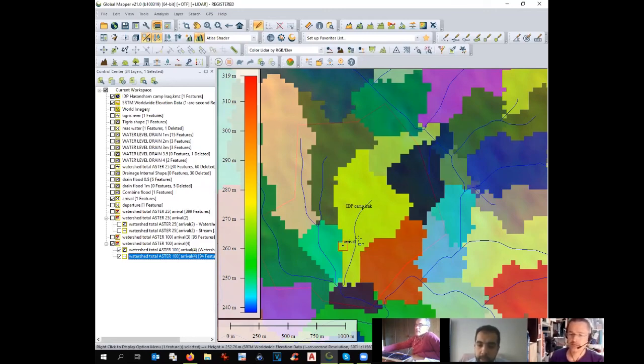You can arrange it, and then once you arrange it, you can make a new digital terrain model and simulate again to see if your arrangement was properly planned or not. For example, establishing a siphon or culvert. You can move the location of the stream, of course, but you have to intervene, and this costs. We have to invest in changing the natural pathway of water. If there is some peril, then we have to assume some solutions.